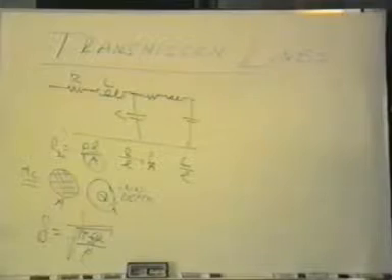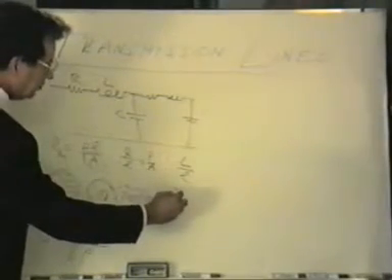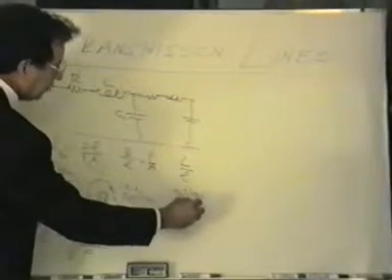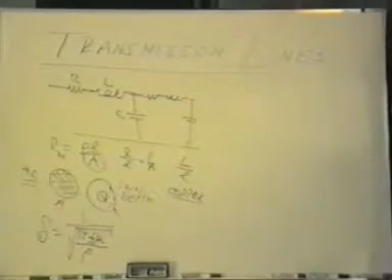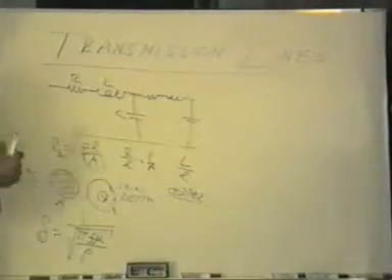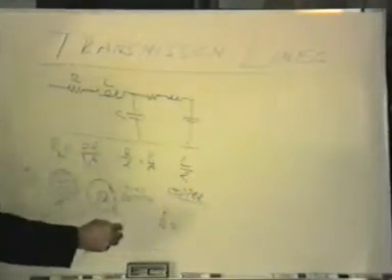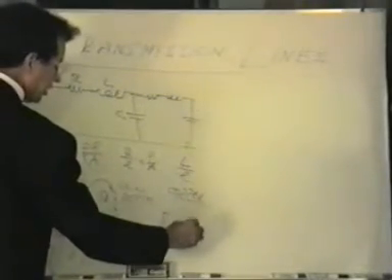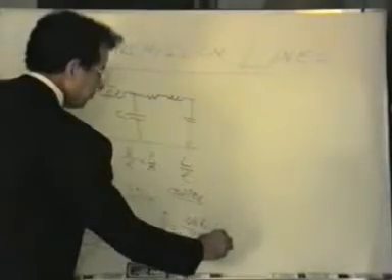To give you an idea how some of these numbers would turn out, for a piece of copper, for which we know things like the permeability and the resistivity, if we were to put those numbers into this equation for skin depth, we would find that delta for copper turns out to be 0.066 divided by the square root of F meters.